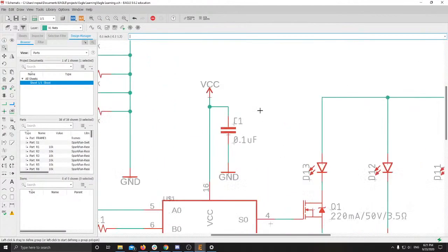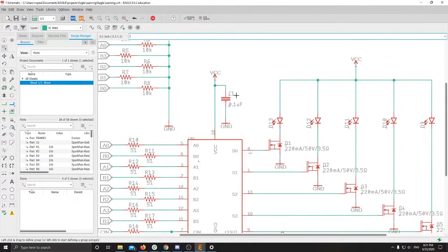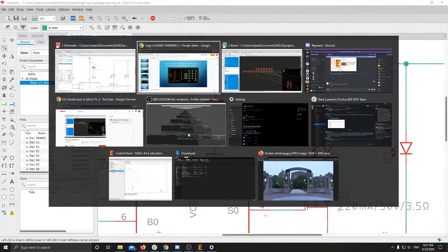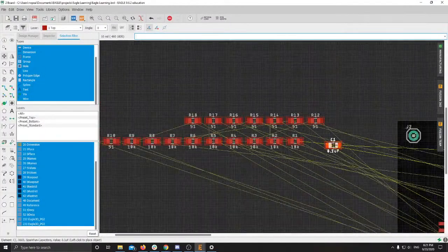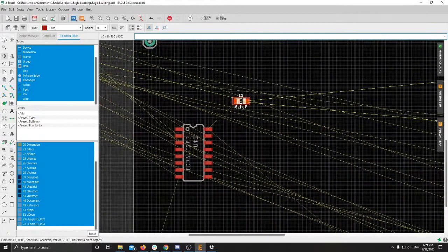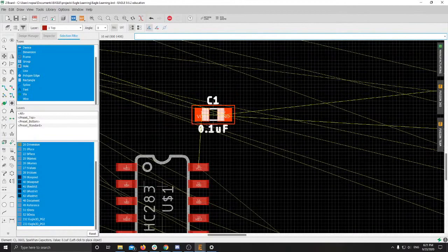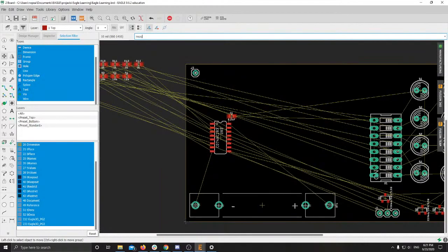One thing too, this capacitor on this package, you want to put pretty close to these pins on the actual package. Just functionally as a circuit, it'll work better if it's closer. Referencing back to your schematic can be good, so I can see, okay, this connects to here, but I want it to actually be pretty close to my power and ground connections, so I am going to put it right here where I can do that.